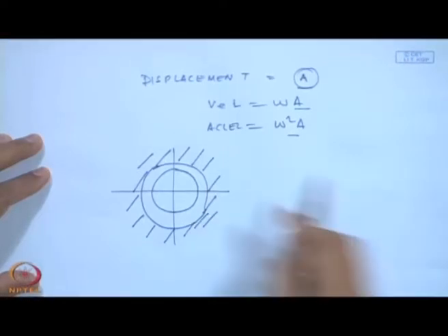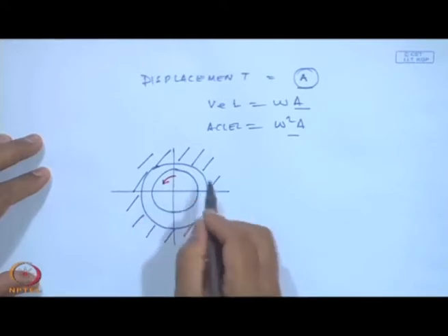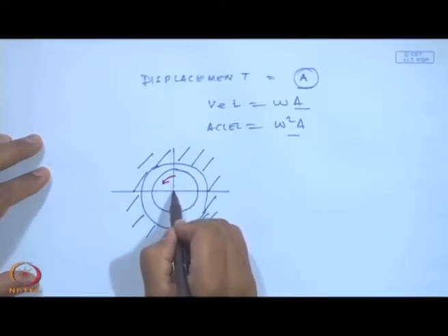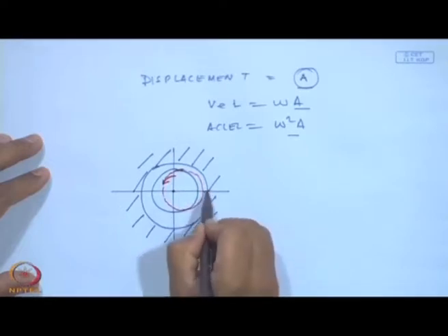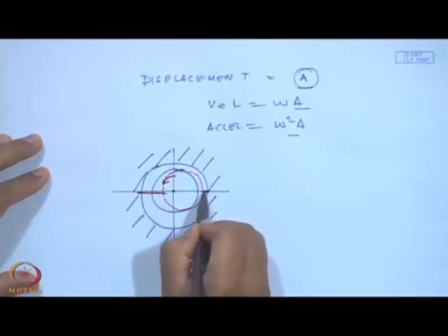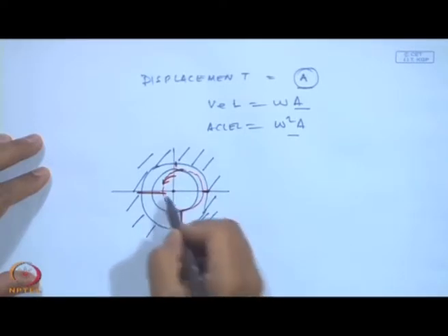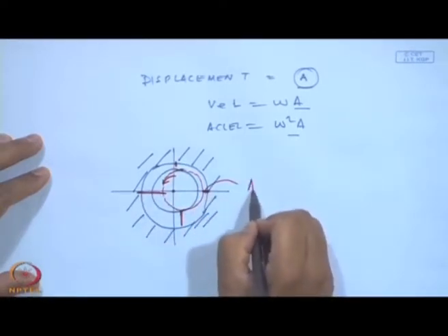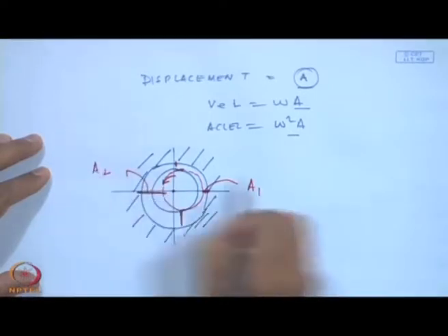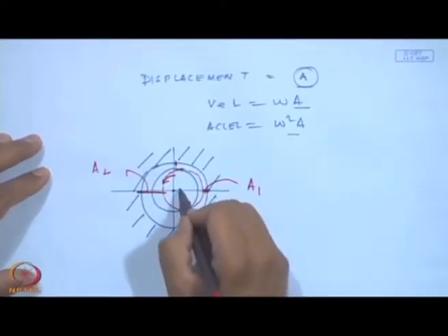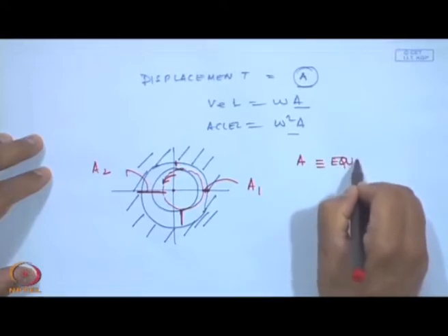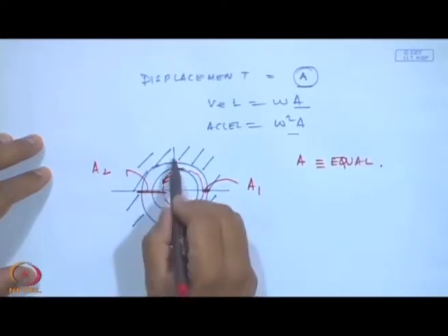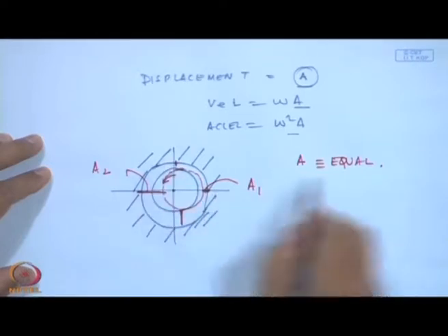What could happen is, this shaft while rotating, if it is not rotating at its center, there may be a subtle slight eccentricity, okay. And because of this, at any of the points you will see that displacement at one location is A 1 and another location is A 2. For the shaft to be uniformly or concentric to the center, all these A's should be equal if you measure in the four quadrants or four directions, okay, at 90 degrees to each other.